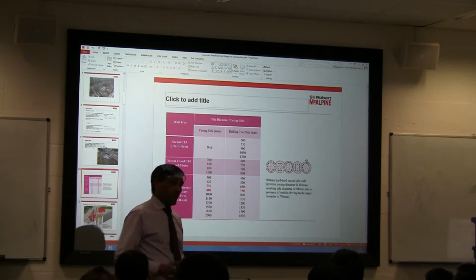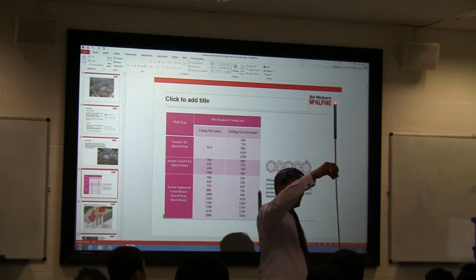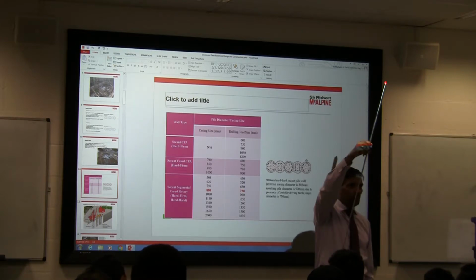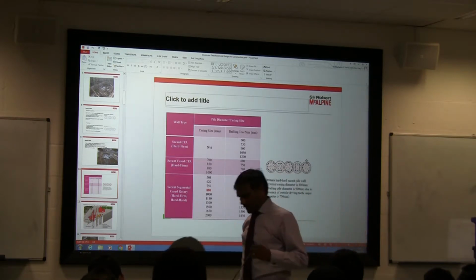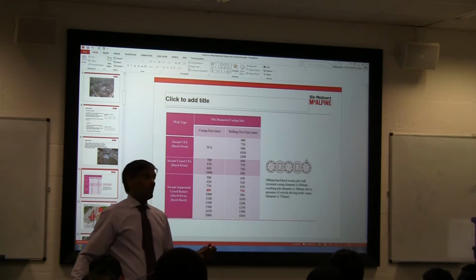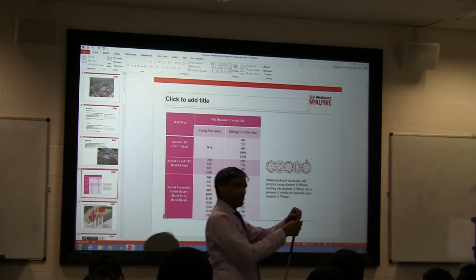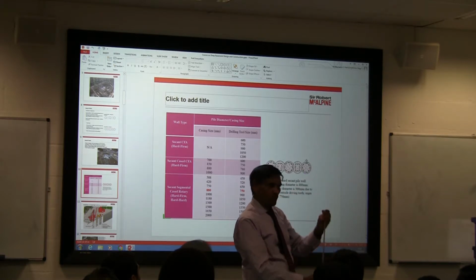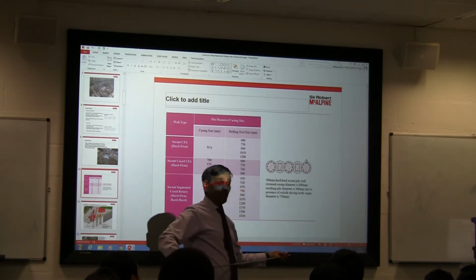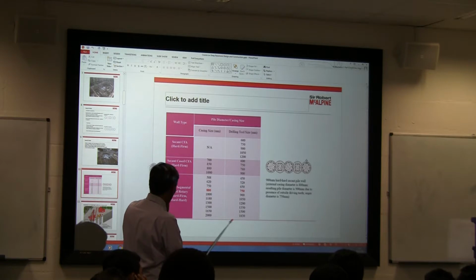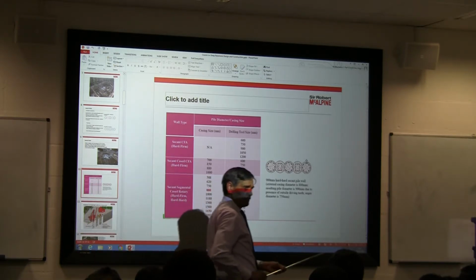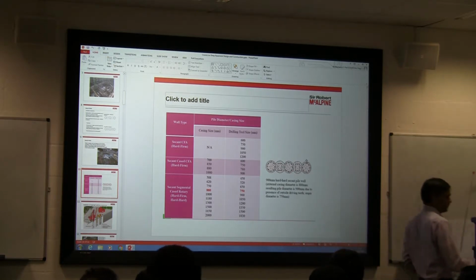If it is too deep, I can't bring this one 26 meters long, hold it up in the air and bring it. I can't do that. It's too high. And then working in conditions like that is very difficult. So what we do is we bring in pieces like this. Small pieces, attach another one, and keep going all the way down wherever you want to go. So that's where it is important that we use segmental casing. As you can see, there is a relationship between those two. That's what we use. Make sense? Great, very good.